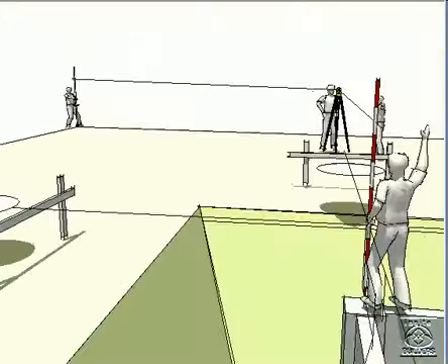It's therefore a matter of transferring the sea level elevation horizontally from the reference point to the formwork of the raised slab. The general idea is to set up a transit or a survey instrument so that it can read an elevation off a story pole over the work point.